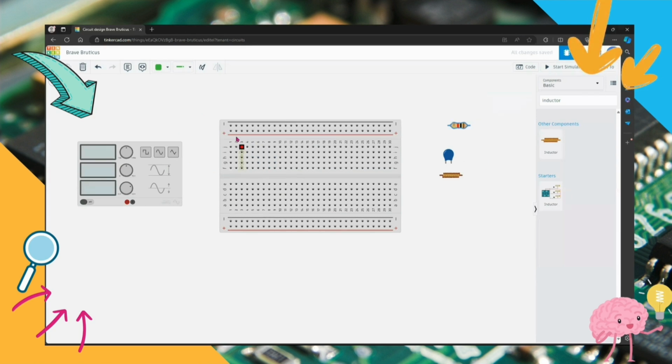So now we are going to connect the input voltage supply with our breadboard. For that we will use the normal wire. There are other possible options, but for our case we will just use a simple normal wire connection. So we will simply click on that and drag it, and connect it to the positive terminal, or where the positive is mentioned in our breadboard, just for better reference. Similarly we will do the same for the negative terminal, and we'll connect like that.